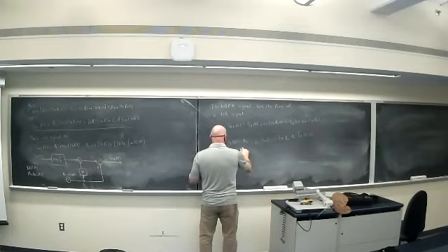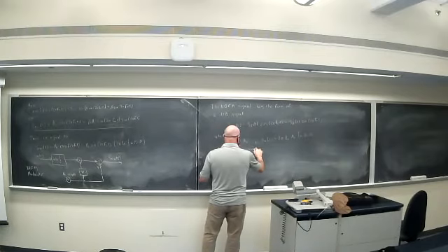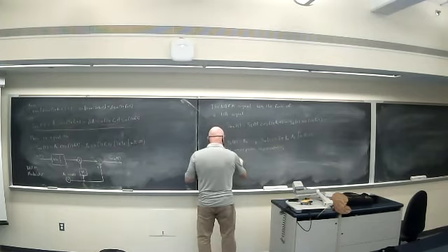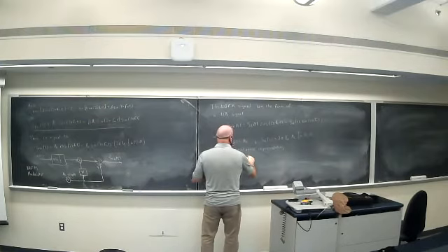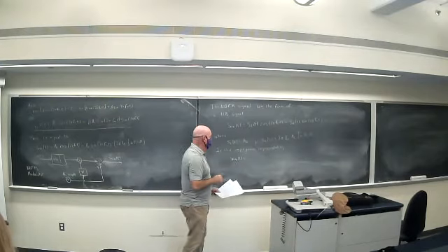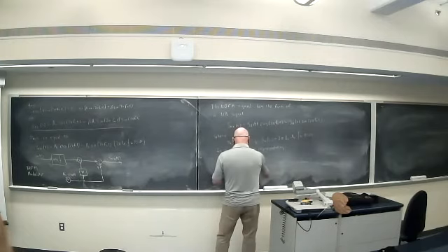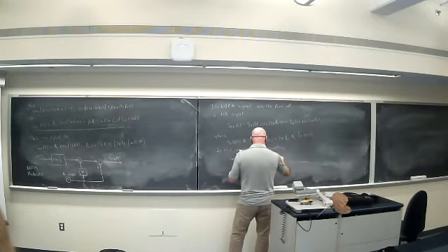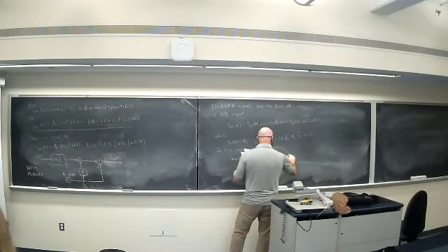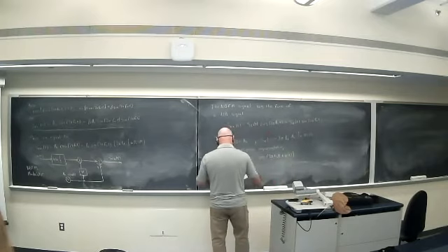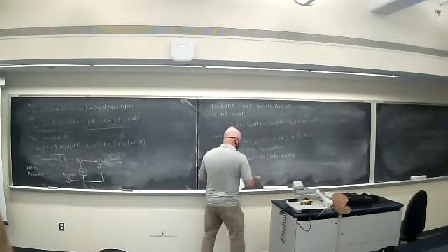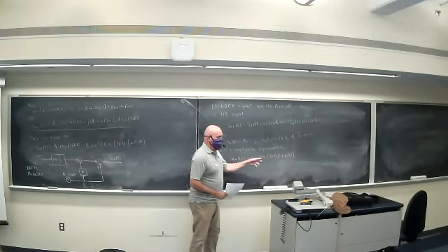So in the amplitude phase representation of the narrowband signal, that's yet another narrowband representation that's related to this one. It's called the quadrature representation. We have A(t) cosine of 2 pi fc t plus phi of t, where this looks like a general modulation signal, right?